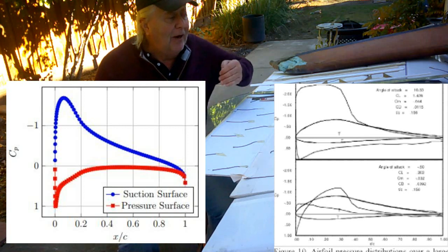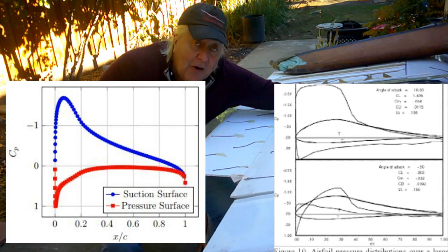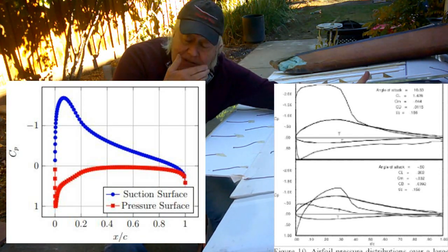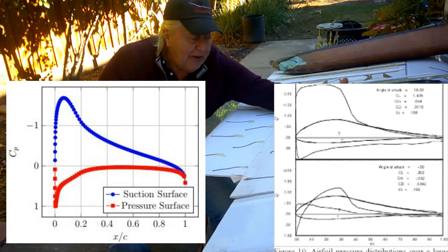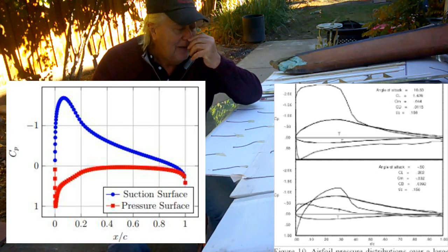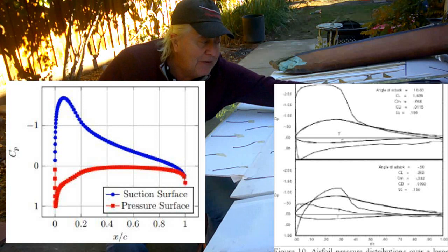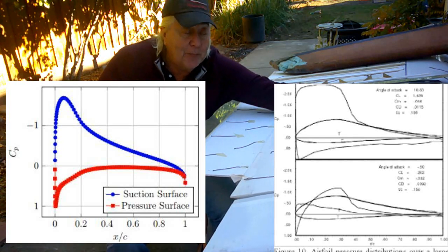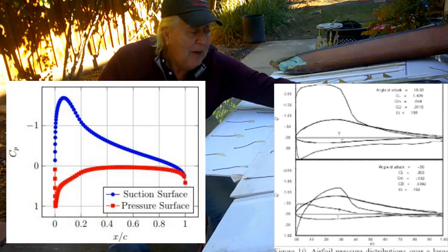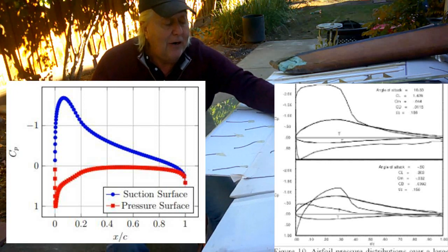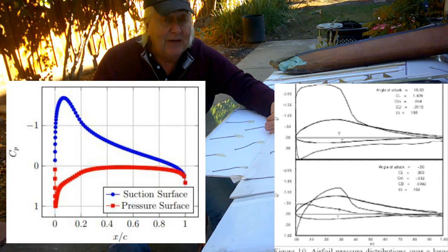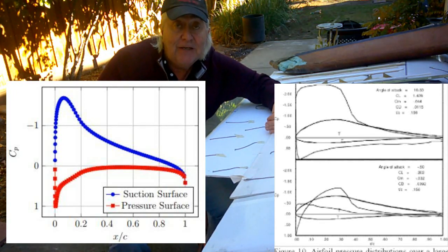And I've talked before about how the flow coming off of the leading edge of the wing has got to penetrate all of that adverse pressure gradient. So it's going fast up here, but the pressure is low, and it's got to push into this pressure gradient as the pressure goes up. Pressure's going higher, higher, higher, higher as it comes back to the trailing edge. And it takes energy to push into that adverse pressure gradient.